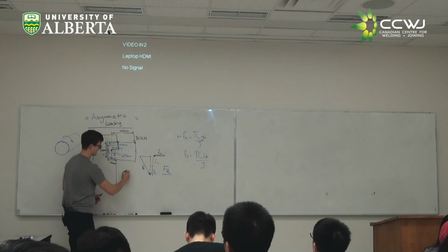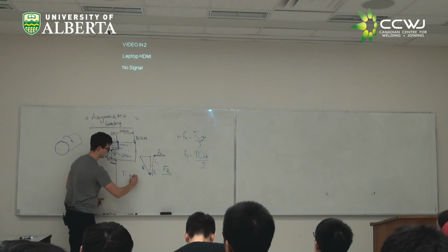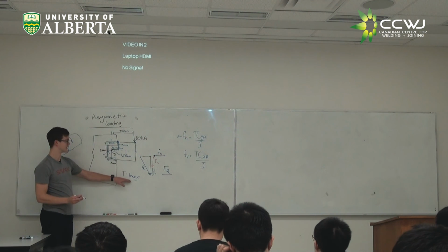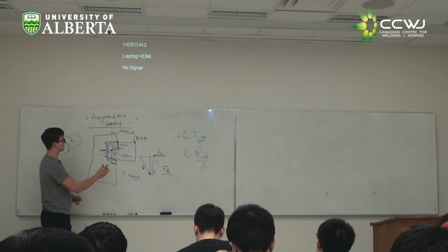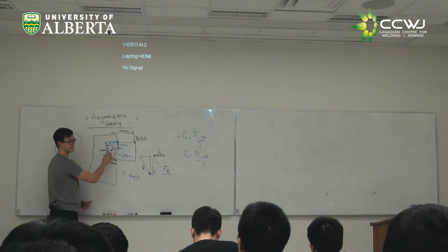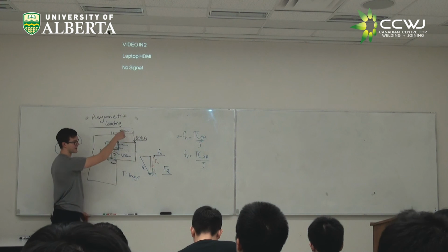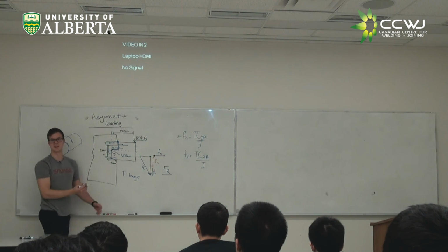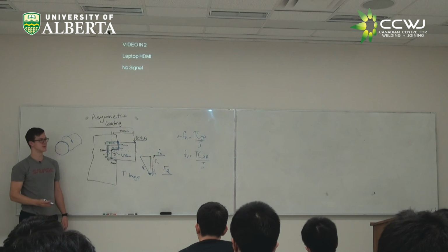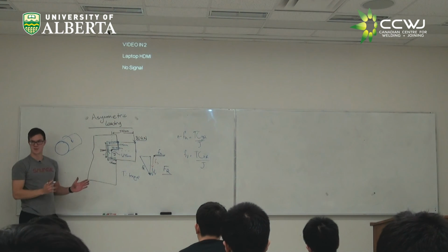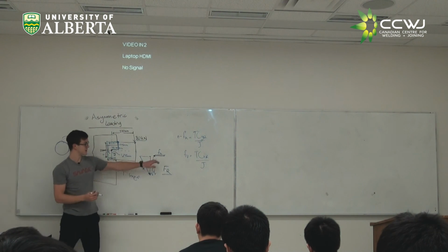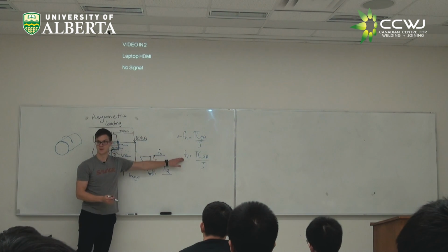T is torque, or moment. But it's called T because it's standing for torque. Our moment here, we have a force, we have a distance, our center of gravity. Because our force is totally vertical, it's a very easy calculation of our moment. It's going to be 80 kilonewtons times 250 millimeters. At that point, we've done all of the hard work of this problem. We substitute in, we solve our FH, our FV.